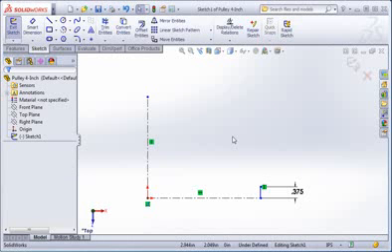Now we're going to work on the sketch for the pulley, and along the way you'll learn about inferred and automatic relations. If you recall, the sketch was fully defined after we drew the construction lines, and then it became underdefined when we drew the standard line. The sketch also jumped above the rollback bar when we added the dimension to the line. It's always helpful to understand how the SolidWorks interface changes while you work, so that's why I'm mentioning it.